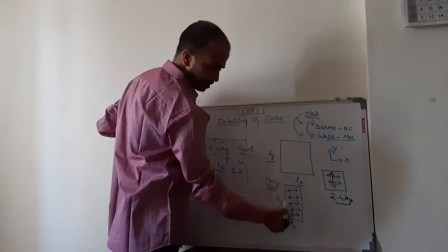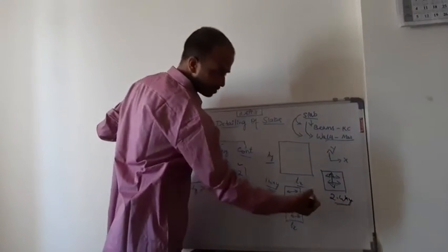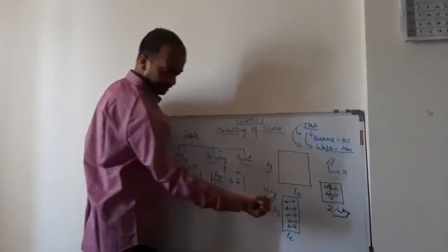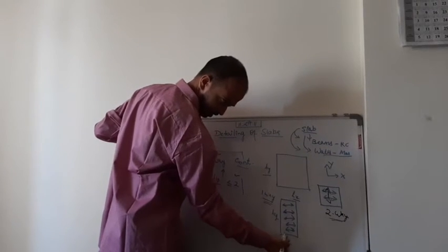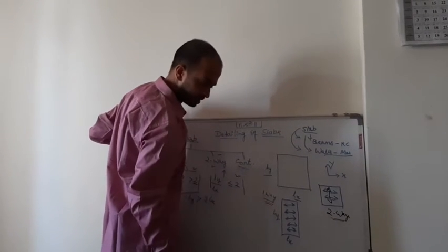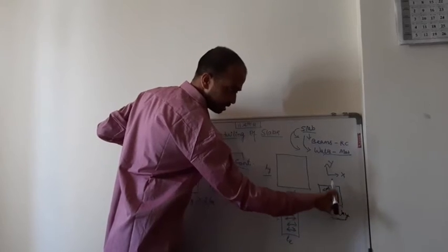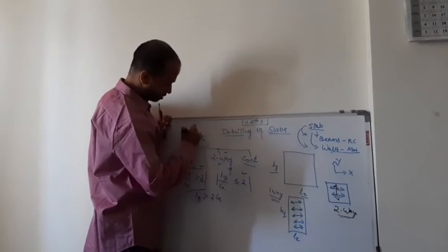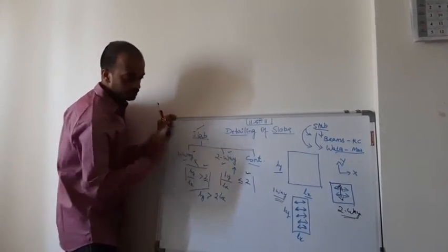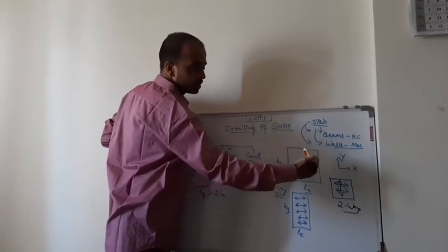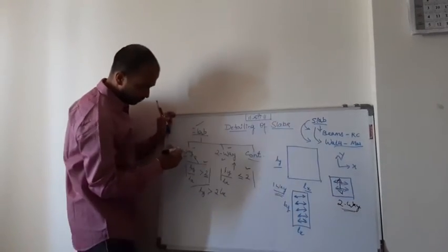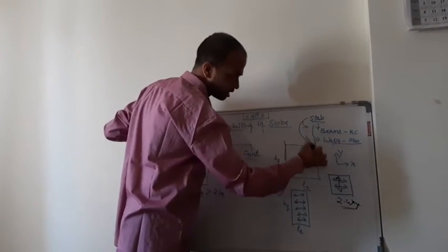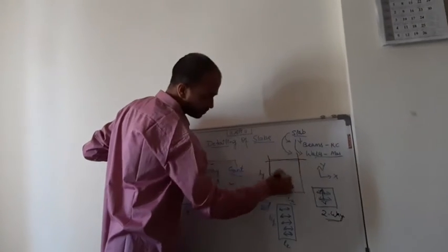The other way is from the given dimensions, draw the plan, and identify Lx and Ly. If the direction is along only one direction, that is along the shorter span, then it is called one-way slab. If the load is traveling in both the directions, then it is a two-way slab. So this is a basic introduction about the slabs, that is one-way slab and two-way slab. Continuous is simple, so it will be continuous over the multiple supports. So for one-way and two-way, we usually take two supports. So one is supported on this and the other is supported here, or these two.